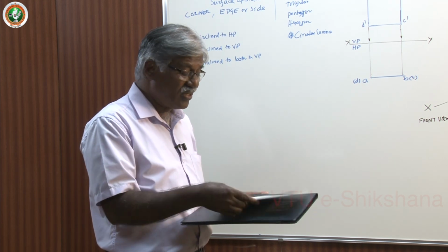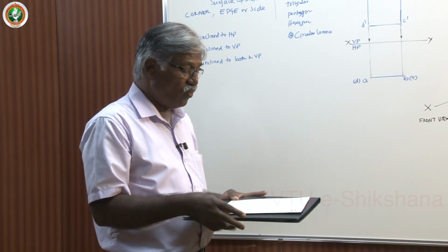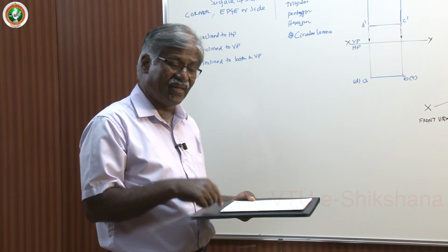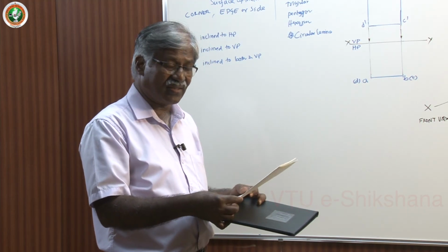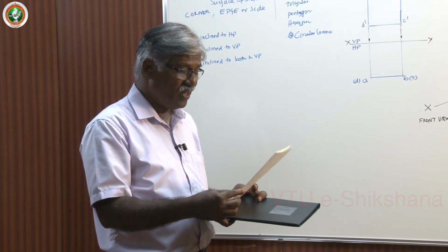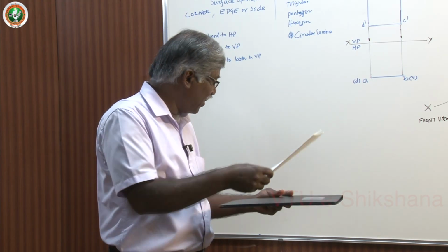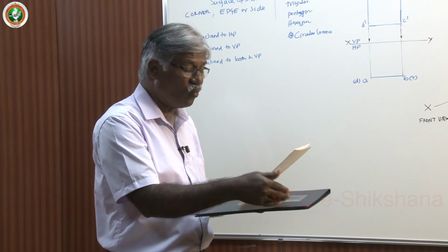Then this is called the surface condition. I always call this a surface condition. Now, what is next? Edge condition or corner condition? Whether corner on ground or edge on. Definitely it is edge on HP. Whether it is the smaller edge or longer edge, let's not worry. It is only the edge now. The edge condition with respect to HP. The edge to be placed on HP is always perpendicular to VP, so that we can rotate about that and get the surface inclination only with respect to HP.